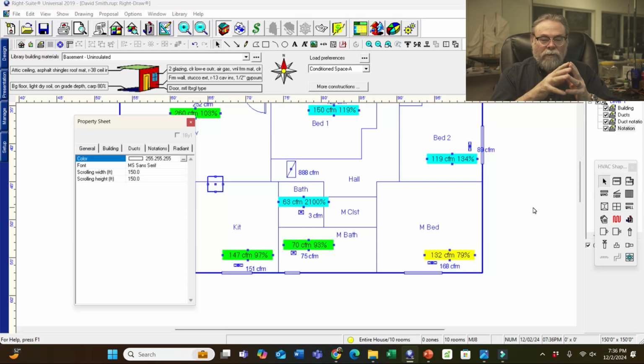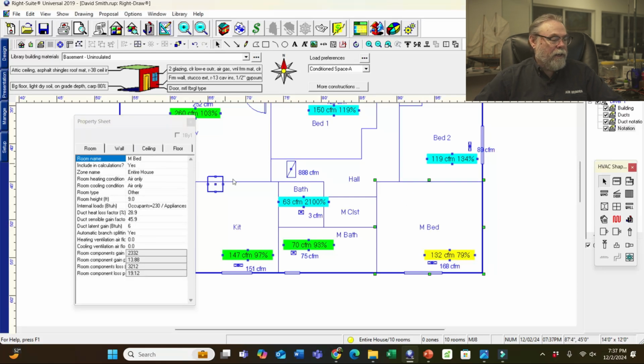If there's angles in rooms and stuff, like say this wall was corner to corner here, I can come in here and grab my edit points and drag this room over like so, and then I can drag the hallway. You see this kind of stuff sometimes. Let me grab the hallway, hit my edit points. Making 45-degree walls is really easy to do.